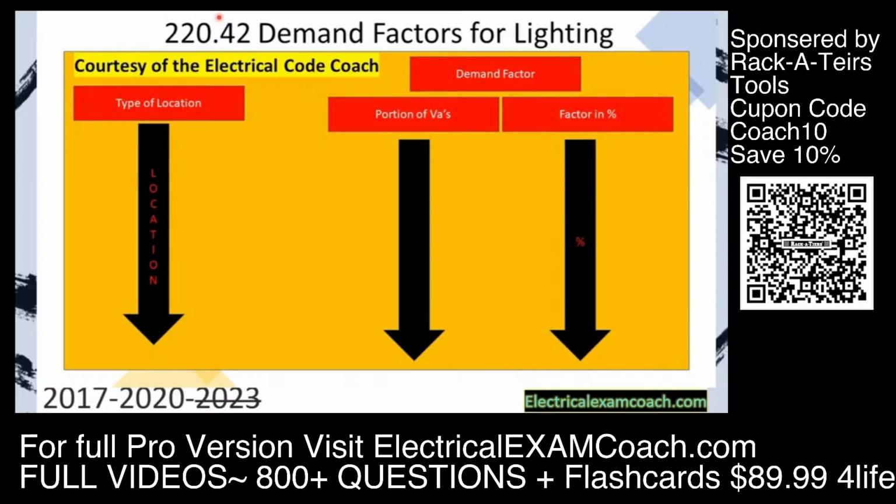Now, you can ask the question, if this is the 3 VAs per square foot, well, it includes receptacles. And you are correct. We are allowed to use this table for commercial lighting or any of the lighting in the following locations that we're getting ready to talk about. But we're also allowed to use it for the entire 3 VAs per square foot, plus the 4,500 that we tacked on for the 2 small appliance and 1 laundry.